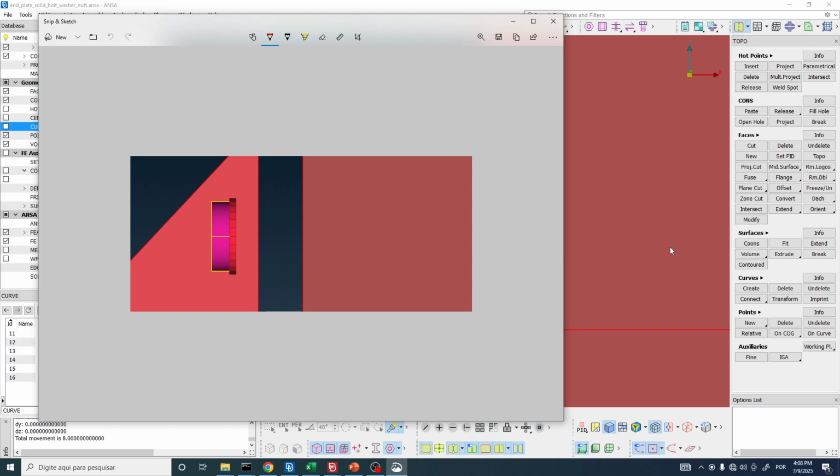Okay, so this extrude that we are going to perform is going to start here, right? We have this thickness here, which is 3. And then we have this distance here until here, which is 20, which is the thickness of this plate. And then again, 20 here, right? And then we are going to have the nut.